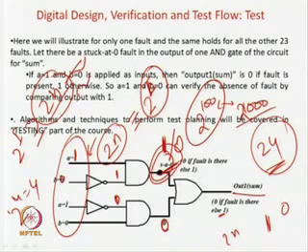So you will be very much surprised that 2n will eventually come to very much less than n by k. It will be a very small fraction of n because of fault collapsing and equivalence of faults, that is, one test vector can test multiple faults. So we will find that from 2 to the power I we will come down to the n by k level.